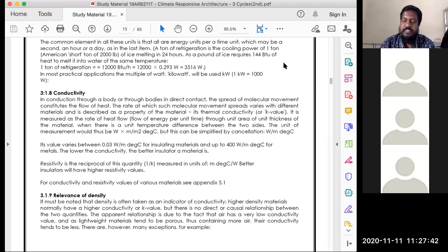No, it can still be taken up. The only condition is, since the K value is so high for steel, we have to bring in an insulation, another material, glass wool. The glass will have a much lesser K value, so the heat from the steel doesn't penetrate into the inner surface. So that's how the treatment goes. We work on the K value for each particular material, and then we design our building units.